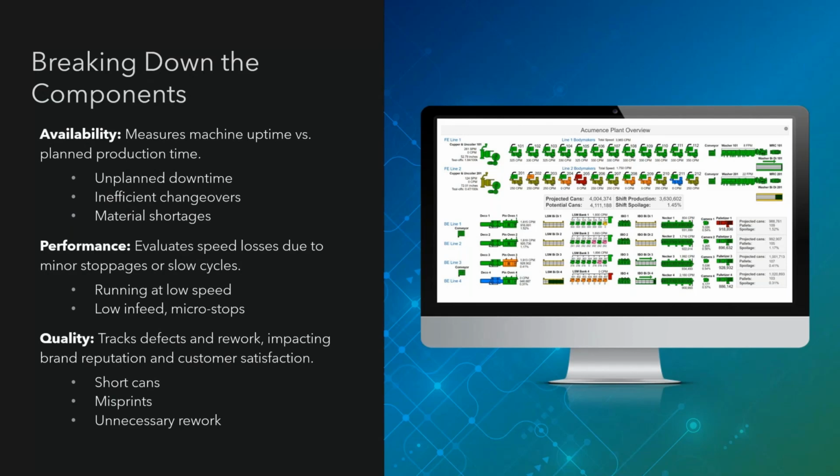Now, another aspect of OEE is performance. So people and operations. Now, we all have goal cycle times, takt times, standard operating procedures for potentially loading parts or inline logistics. And this is what performance really captures. Are we falling short on takt times? Are operator cycle times going past their ideal state? Do we have stoppages such as shortages of parts from inline logistics?